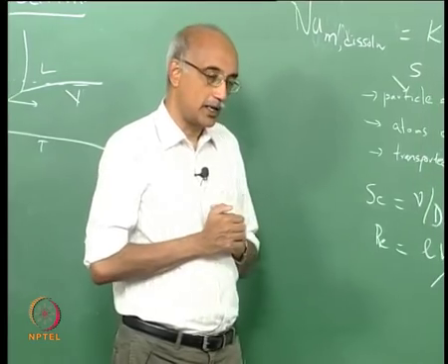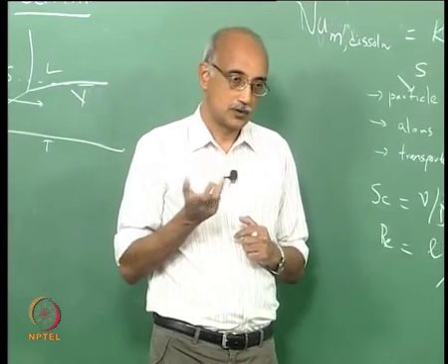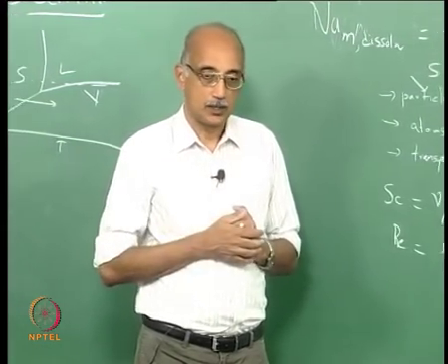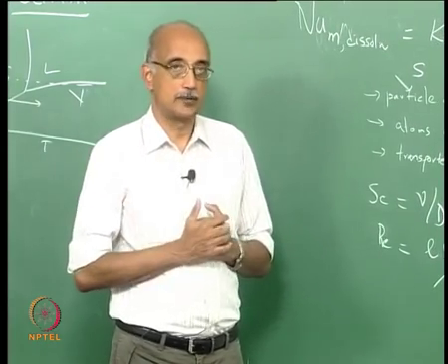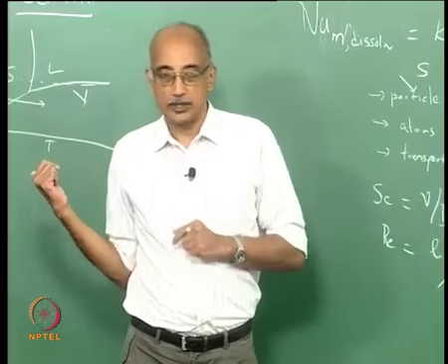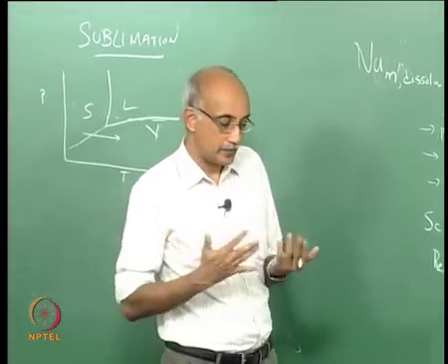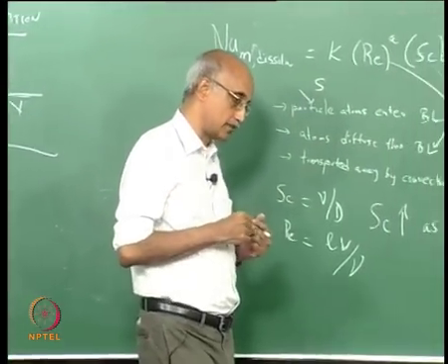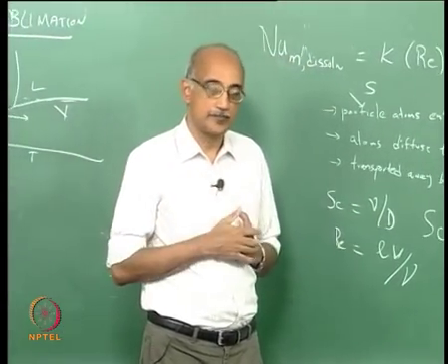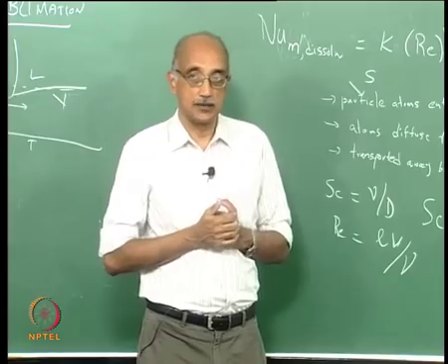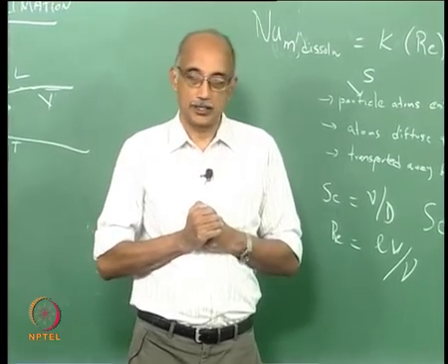On the other hand, the process of fuel combustion can also be governed by convective phenomena. In the simple model that we developed that established essentially a quadratic relationship between particle size and burning time, the assumption was that convection was negligible.